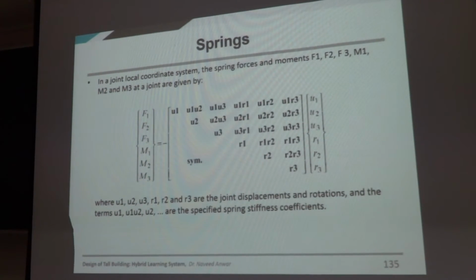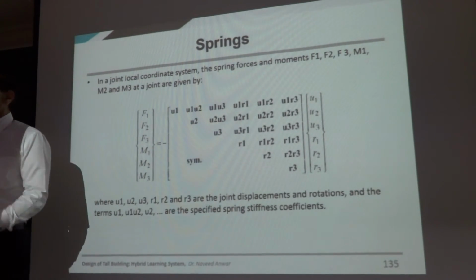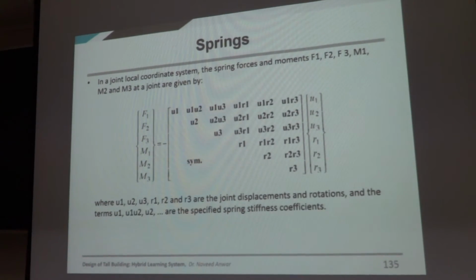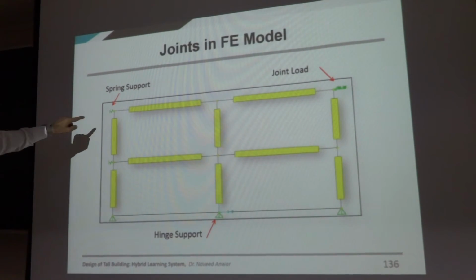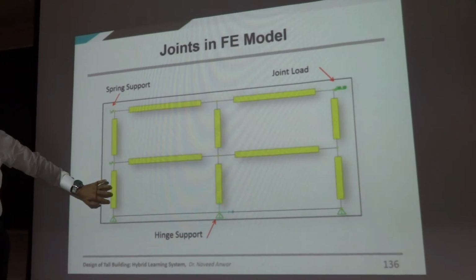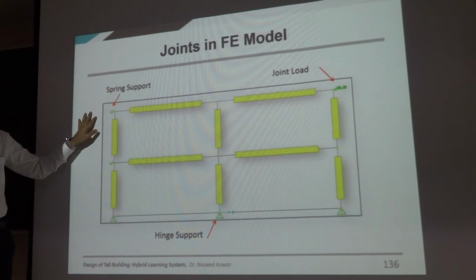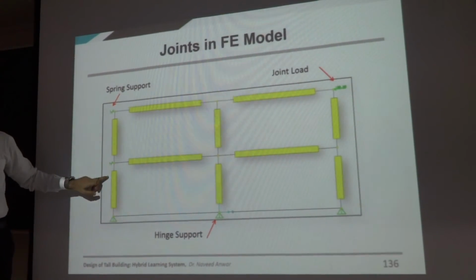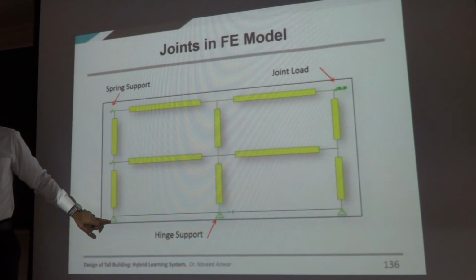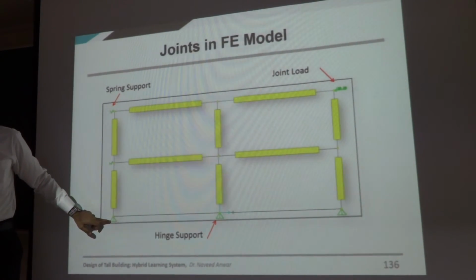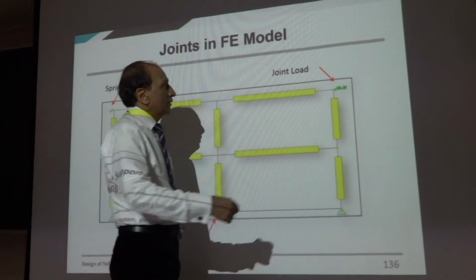Right? So you need to do that. You can replace the boundary by springs, that is minimal. If it is a node, you can put a spring here. Let's say this is a basement, and then there's soil here. You can place the soil as springs at the node. For boundaries, you can put very simple point boundaries, which do not exist, but you can assume it is like that. It's fine sometimes, as long as you can model it, or you can apply loads there.